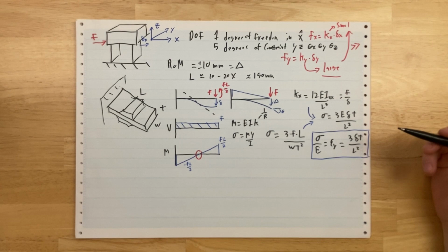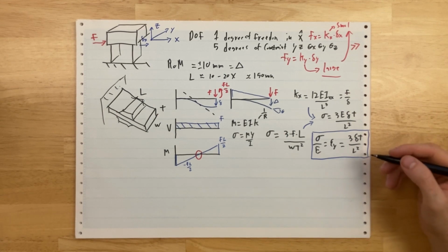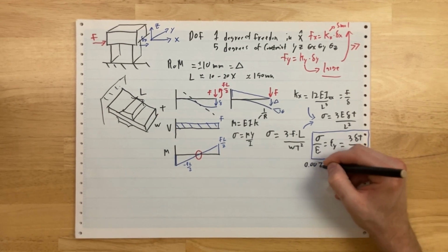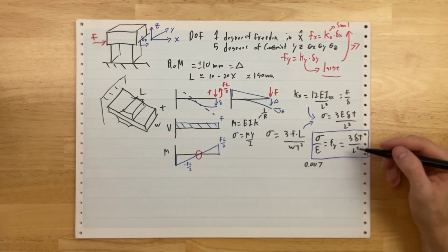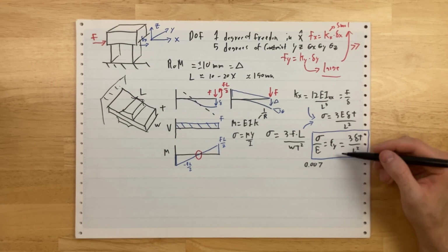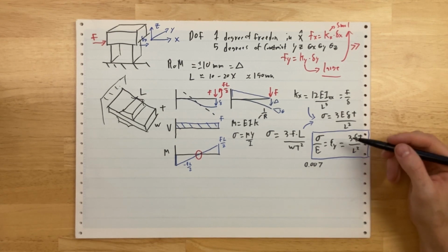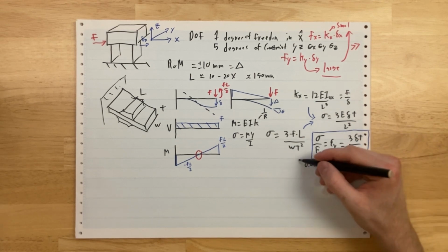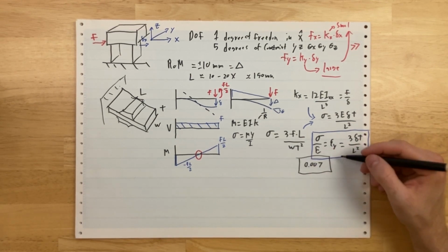Well, we're probably going to make this out of metal if we want good stiffness in other directions. And it turns out that the yield strain of 7075 T6 is 0.007, or 0.7%. That also happens to be the yield strain of grade 5 titanium. It also happens to be the yield strain of a really good hardened steel, something like 4340. So practically, if you're taking a metal to the limit, you're going to get about 0.7% strain.